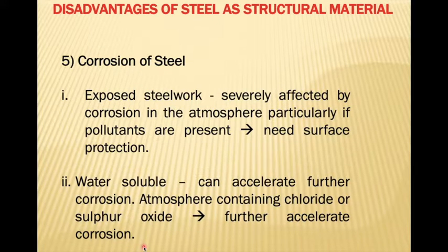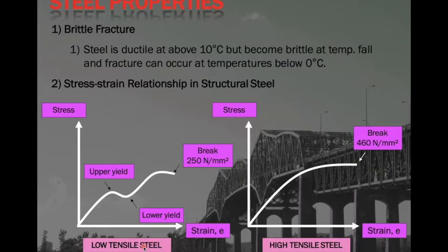For marine structures, usually we will not use the steel structure unless it is fully protected, because it is under a chloride environment. Therefore, it is much easier for the metal, the steel, to corrode. And this is for the steel properties.